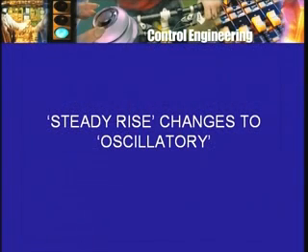But if Ka is too large, then the speed will change from 1500 to 1510 perhaps, not steadily but in an oscillatory manner, so that during the transient period the speed may go beyond 1510 rpm, may go to even say 1600 rpm, then may go below 1500 rpm and go on oscillating like that till finally it reaches the value after sufficient number of time constants of the new value 1510 rpm.